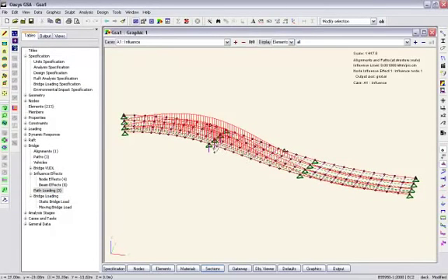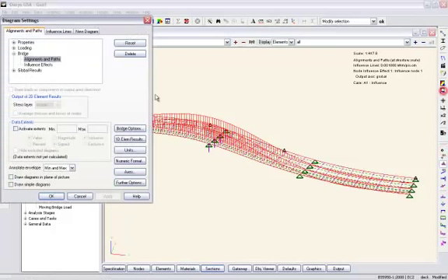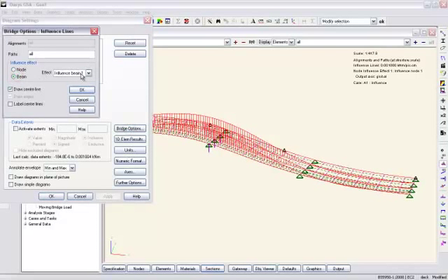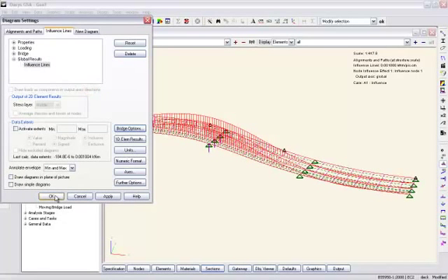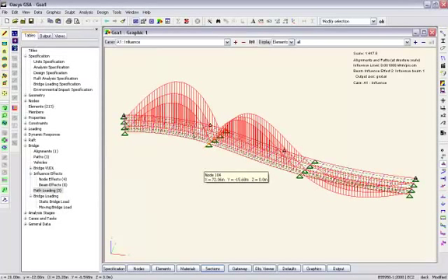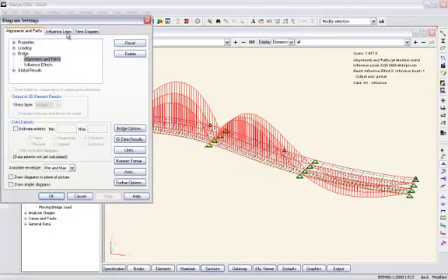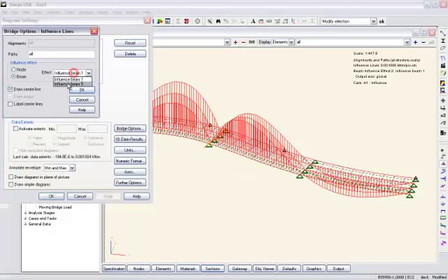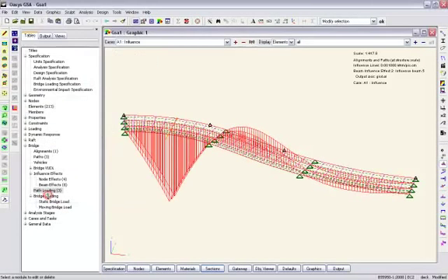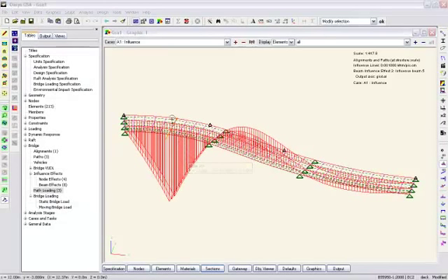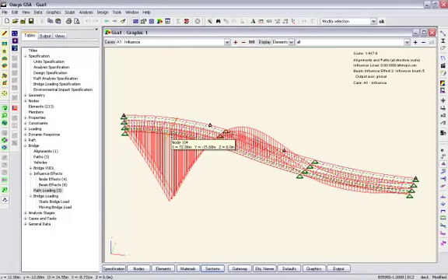So here is the influence line lobes for that support point. And if we look at the influence line for the hogging at the beam, you see we get 2 lobes at that point, and similarly for this mid-span moment.